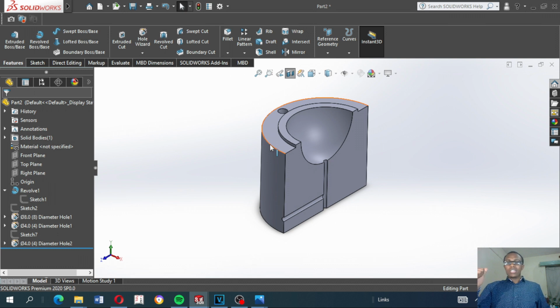One is for the safety of the guys doing the machining. This product is an aluminum product, so it's not going to be so much of a hazard to whoever will be handling it. But if it were made out of steel, sharp edges on steel have a tendency of slicing through things, including skin and gloves. That is if you are wearing pretty light gloves. So for that reason, we'll knock out the edges, and the way we do it is we use the chamfers and fillets.